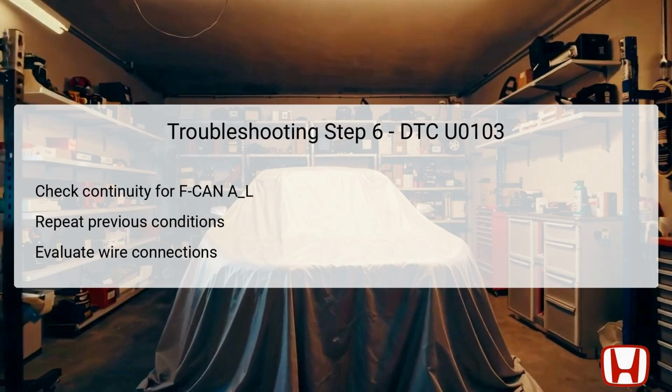During the sixth troubleshooting step, you will check for continuity in the FCAN-AL line, which is crucial for communication between the shifter control module and the TCM. The initial conditions remain the same. The vehicle should be in off mode, and both connectors should remain disconnected. This time, test continuity between test points number 6 from the SBW connector and number 47 from the TCM connector.